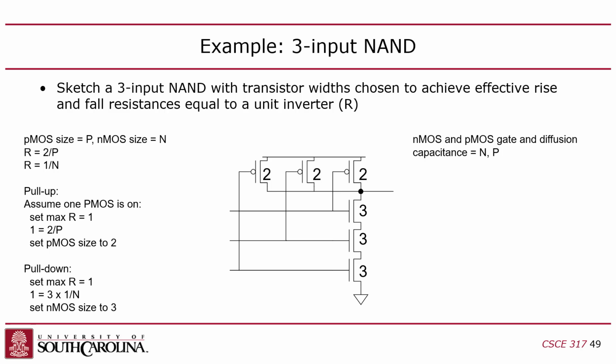This is why we had before, remember, propagation delay and contamination delay. This is one of the reasons why we have a difference between contamination delay and propagation delay. Because this guy has these in parallel, he may be able to pull up faster than he can pull down, right? So the pull up time may be the contamination delay and the pull down will be the propagation delay, right? I think that's how it works out, but let's find out.